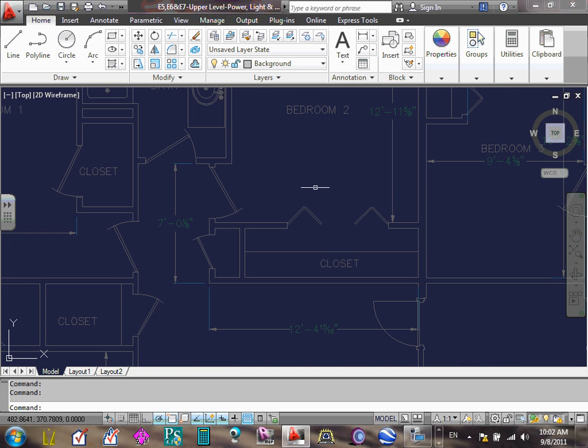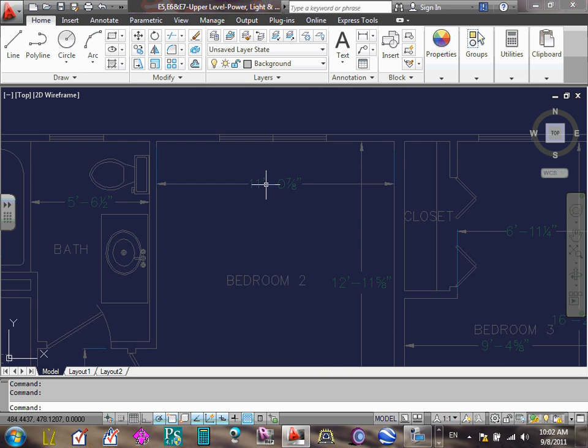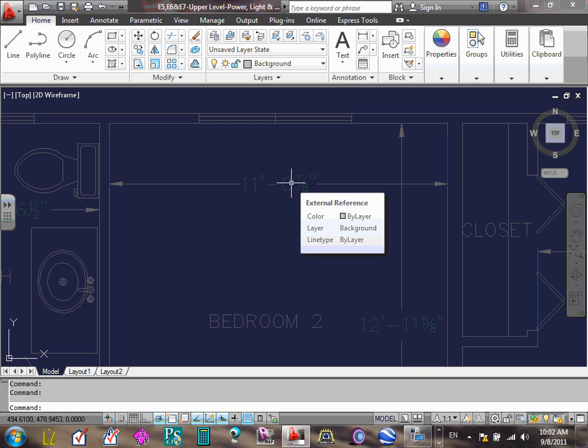Don't worry about the dimensions. Chris, can you see that the dimension is still green, right? Here's what I do with the dimension. I leave the dimension until the end, and then I turn the dimensions off. The dimensions are so cool, Ashley, for when you lay out your receptacles. It gives you kind of proximity where you are. So you leave them on so you know how to lay out 6x12 rules. And then before we print, we just go to the dimension layer and turn it off. So don't worry too much about the dimension.